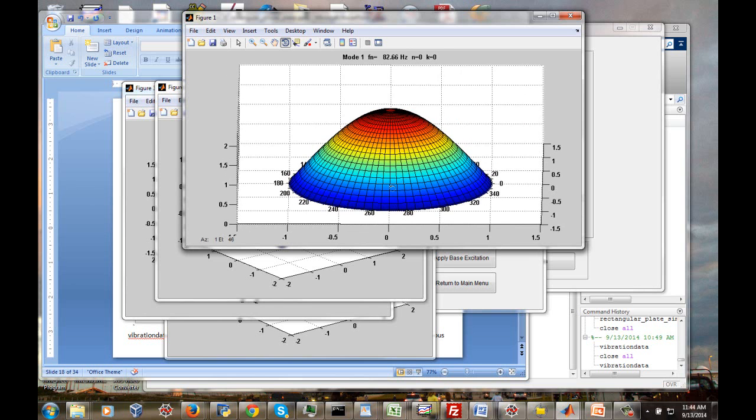So what does that mean? Well, because our von Mises stress depends on both hoop stress and radial stress, the peak von Mises stress does not happen at the center of the plate. Rather, it happens somewhere that's off-center. More about that later on.